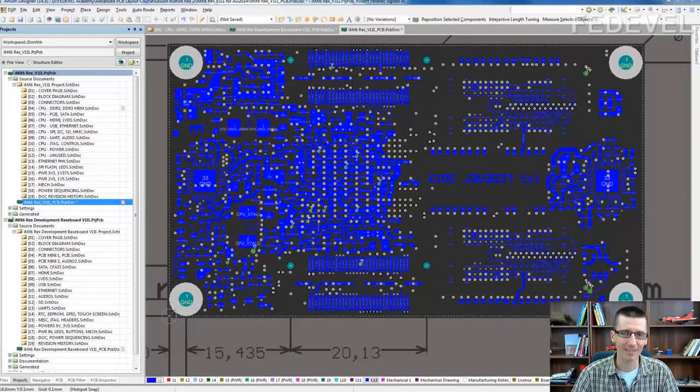Okay, sometimes I do use ground planes on the top or on the bottom layer, but it is only because it is required for some reason. For example, this ground plane can sometimes be used as a heatsink. In the case when I use a ground plane on the top or on the bottom layer, I always place a lot of ground vias there, so I'm pretty sure the connection of this ground plane is a really good one.